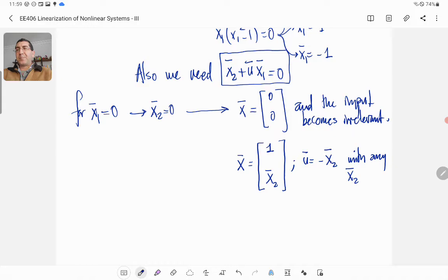And just to give you another example, this is also the case for a transistor circuit. Basically, you create a DC offset condition. That means you generate a DC bias, which is, in a sense, the equilibrium input. You create an equilibrium point around any chosen state. And then around that state, you can approximate the system as a linear system, and you can do all kinds of small signal amplification and things like that.